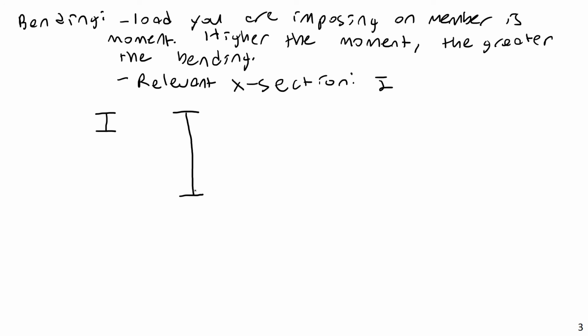And fundamentally, this is what moment of inertia represents. Now, of course, we could talk about it in many different ways. But when I think of moment of inertia, I think of it as the ability of a cross-section to resist bending, or for a given object, what portion of its bending resistance will come from cross-section rather than, say, material properties. Okay, so there's that.